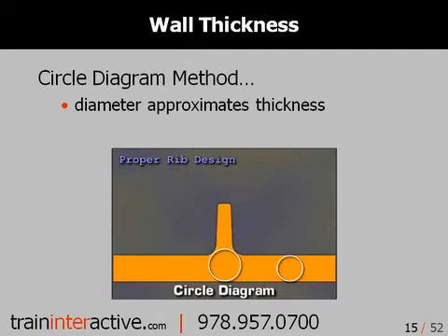In this representation, you'll note that we have simplified part thickness with circles. For those of you who've not been directly involved in part design, we can use these circles to represent the effective thickness of the plastic part in order to estimate cooling time. On the right-hand side, the diameter of the circle is the same as the wall thickness, while the diameter of the circle under the rib is approximately 30% larger.